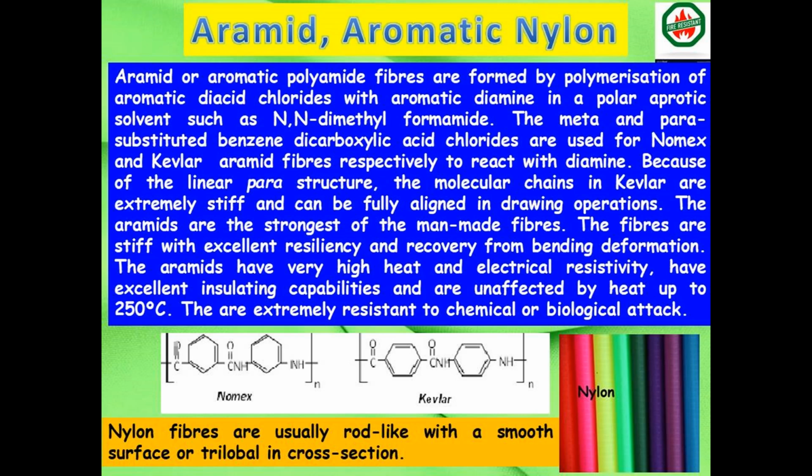The aramids are the strongest man-made fibers. The fibers are stiff with excellent resiliency and recovery from bending deformation. Aramids have very high heat and electrical resistance. They have excellent insulating capacities and are unaffected by heat up to 250 degrees centigrade. They are extremely resistant to chemical and biological attack.